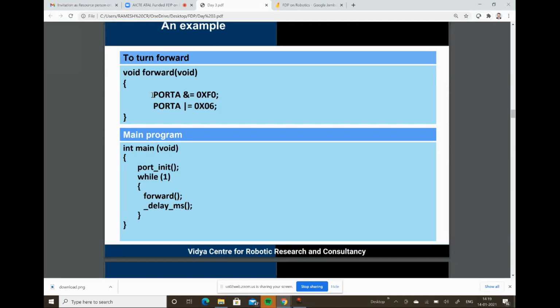In that case, we need to stop the robot for a small instant. Only then can we get the robot's motion in our control. If you suddenly switch the robot to move in a new direction from the current direction, we may not be able to implement a smooth transition in the direction change. That is why I'm initially passing a 0 value, which turns off the robot movement for a small instant, and very soon I'm writing the value for forward.